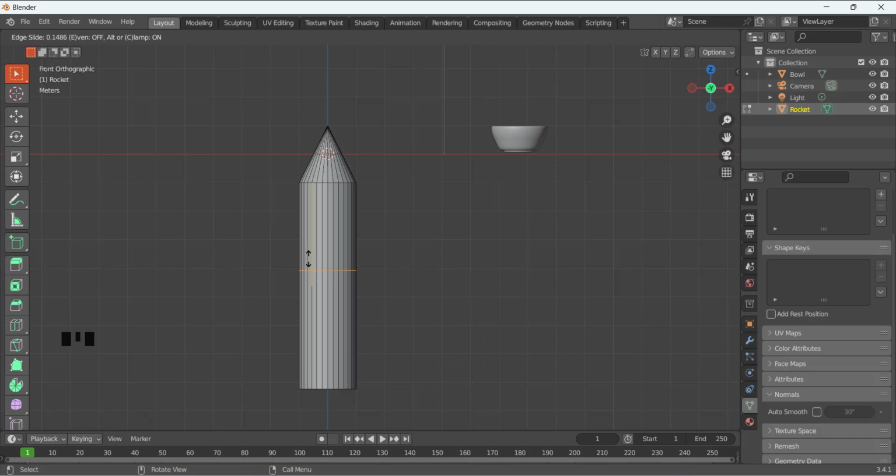So we achieve this goal by using the loop cut shortcut key. By using the tool on this toolbar, we cannot achieve this effect. So I am going to press the left mouse button to place it in the previous location. If you want to place it in this location, we just press the left. And if we don't want to move this loop cut, we just press the right mouse button, so it will be in the same location. So again, I am going to use Control plus R to add this loop in this location, and I am just going to drag it in this location.